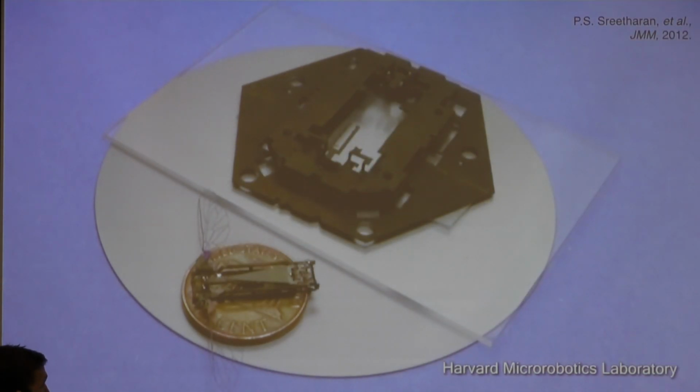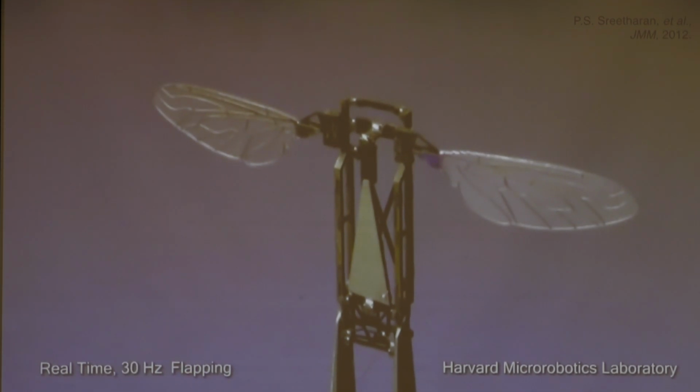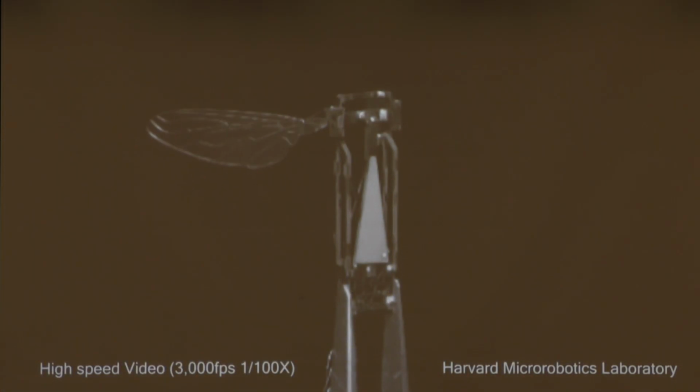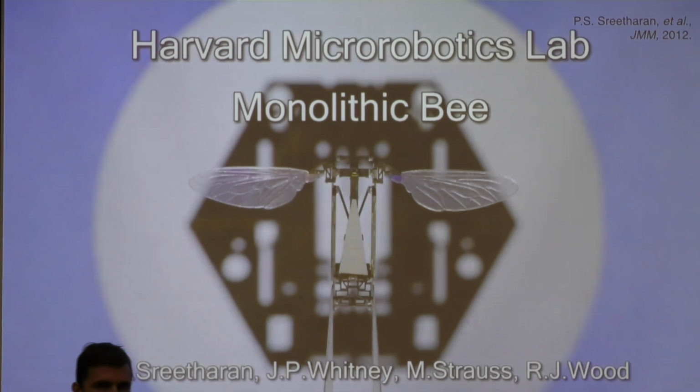And this is akin to a multi-layer printed circuit board, but now the trick is that we are also able to micromachine adhesive layers as well. So we can control wherever we're bonding layers together through the thickness of this material. And that, along with the ability to create structures with any sort of material composition, allows us to create parallel mechanisms through the thickness of the device. So we can create 4 bars and 5 bars or whatever built into the layers of these devices. And these devices could be many tens of layers thick if we wanted.